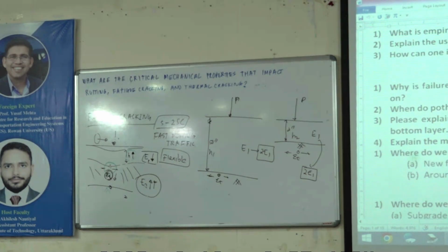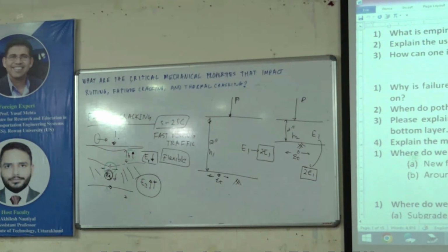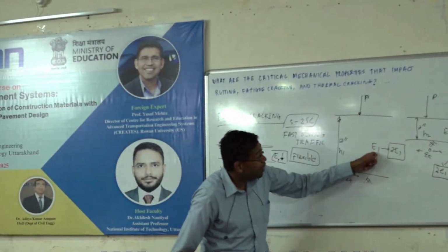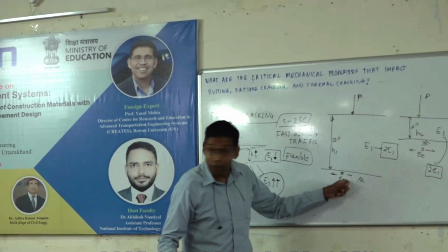So impact in what sense? Like in terms of the increase in epsilon T. Second one, sir. The second one will have the most impact. Why? Because due to higher depth or thickness, there will be less dependency on E1. Yes, first one, 100%. You're correct. So here, going from E1 to 2E1 will have minimal impact on epsilon T.